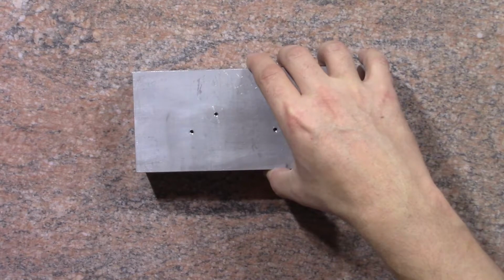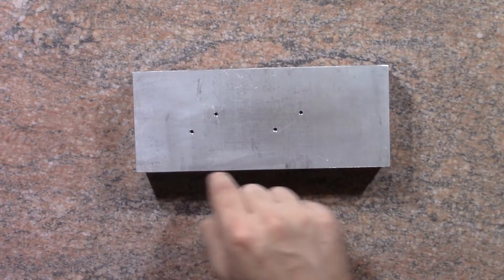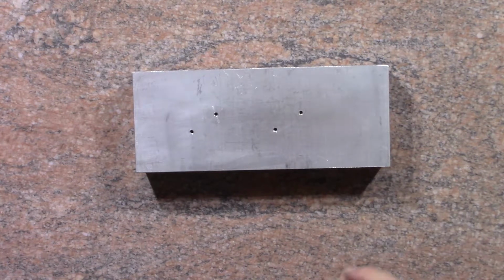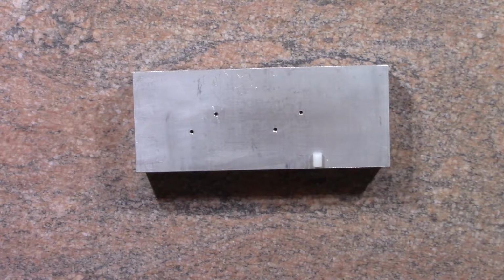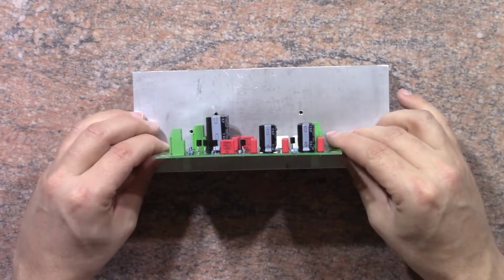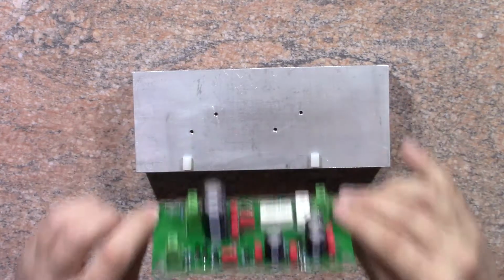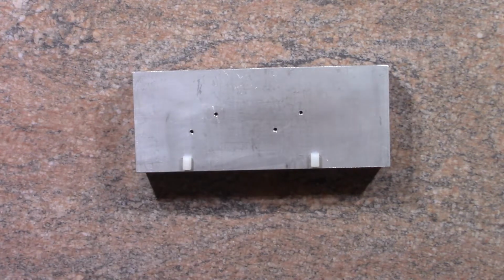So the first thing is, I'm going to use some spacers between the bottom of the enclosure and where the card's going to be, and these are 10 millimeters long, and you can see that's where that spacing comes from. Then the card will go on top like that, and the transistors will screw into the heatsink with these tapped holes. Now I've tapped these holes in exactly the same method as I've shown in episode 2, so you can always go back and have a look at that.